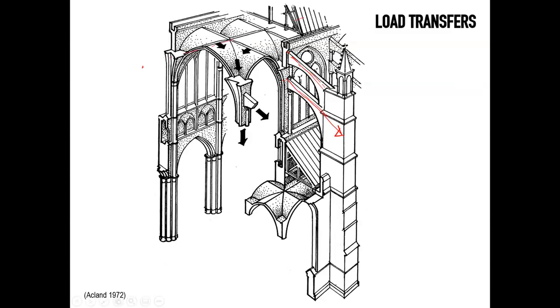They are more like an external pier that normally is aligned with the transverse ribs. And then the pinnacles on top of that add more weight, so that for whatever kind of lateral thrust may come, it adds more weight into this, and it somehow drives these forces all the way down in a way that it's, if not perfectly vertical, certainly still within the main section, at least 1/3 inboard from the edge of the buttress at the base.